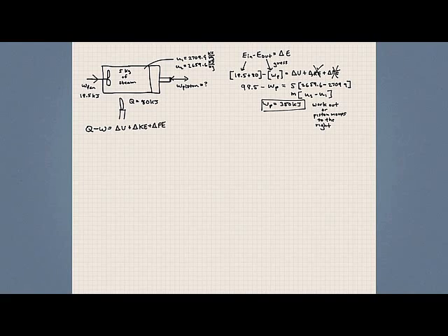So what this is saying is essentially the same thing as what we were writing before, except now I've expressed the energy in and energy out in terms of heat and work, since remember that's the types of energy that we're going to be assuming act on our system boundary. We also have the change of energy that's occurring inside of our system, which is taken into account by the internal energy, the kinetic and potential energies. We've already determined that kinetic and potential energies we can neglect.